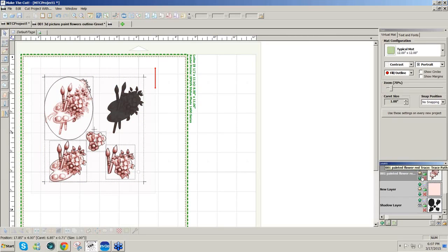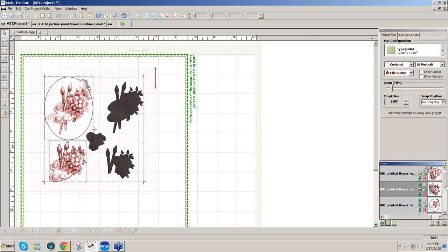you hide all of these, the registration marks move a little bit, just about a 0.100th inch in, and that changes the accuracy of your cut. So I like to use Brian's little trick that he does of making a little extra line here.